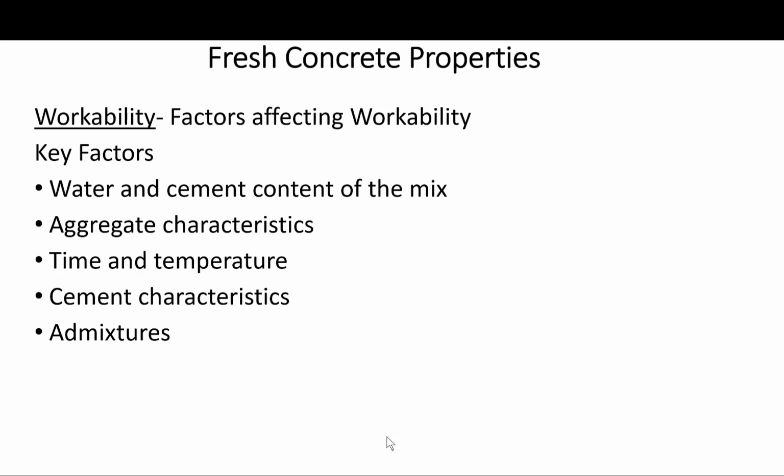Okay, so let's look at the factors. What affects workability? The workability of concrete, as you have probably figured by now, is affected by a number of factors, like water content, of course, and the cement content as well, the mix proportions, the aggregate properties, which play a big role, time and temperature, or basically the ambient conditions, characteristics of the cement itself, and the use of admixtures. All these affect workability. So almost everything affects workability.